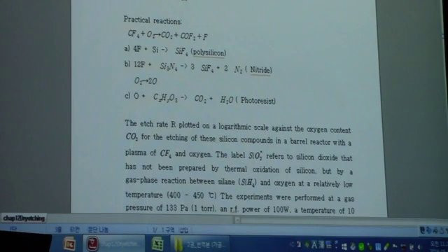Okay, that F is going to react with the silicon to form a gas, silicon tetrafluoride. That is a gas, so it just takes off the silicon with this chemical reaction A. And in the case of a nitride, it forms silicon tetrafluoride, which is a gas again, and then it's going to be etched.